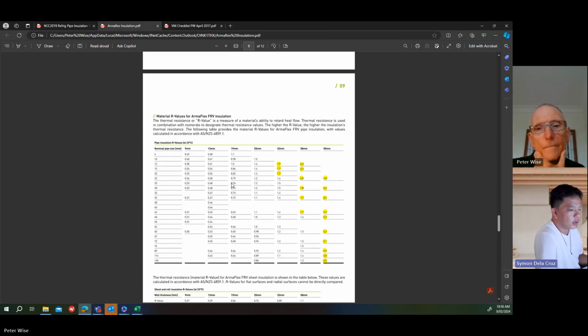Just a question on pipe insulation. Because it is only DX, the material doesn't matter. It is only fixed. We don't need to change it based on the space or area that it is serving, right? It's just the material of the insulation. Well, for DX equipment, it's always going to be Armaflex type insulation, which I think they call elastomeric. It's a rubber closed cell, flexible rubber insulation, which has a vapor barrier as well. So you have to have a vapor barrier. Do you know what I mean by that?